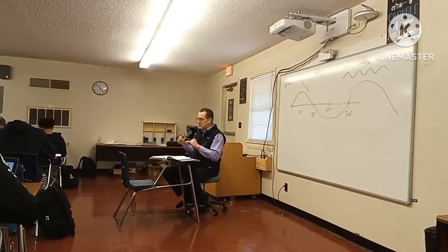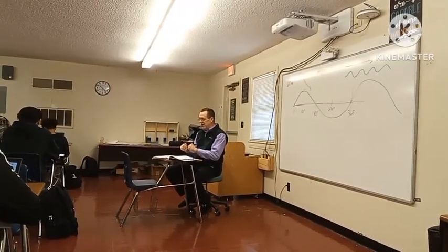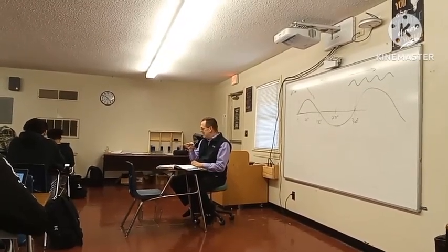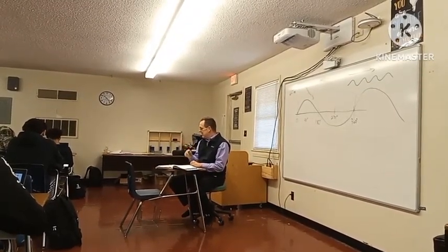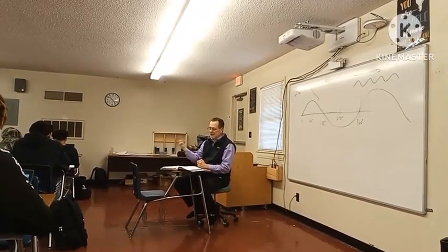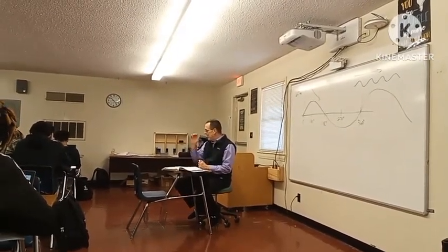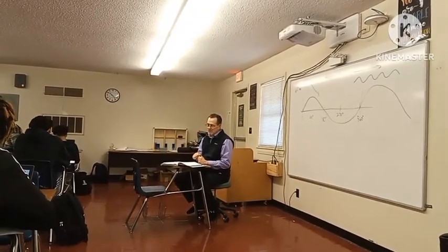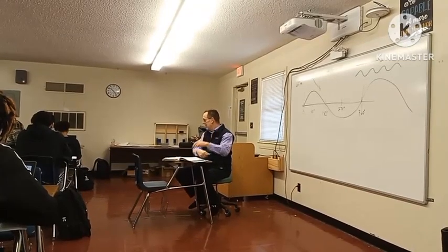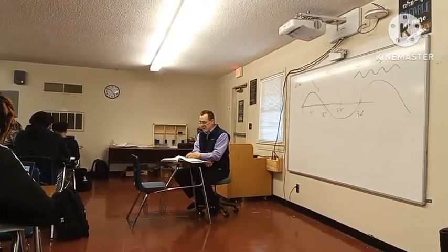That's what you're going to actually be doing when we conduct our test. You're going to take actual voltage readings properly with the meters, record them, and then you'll average out the different voltage readings at different locations, come up with an average RMS voltage, and then you're going to determine what the overall peak voltage values are for that sine wave for the AC that we have going through our classroom and surrounding area.